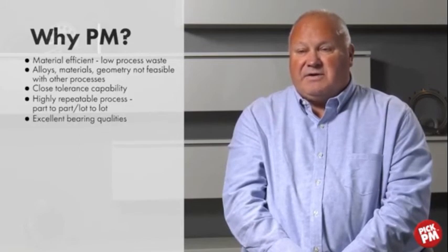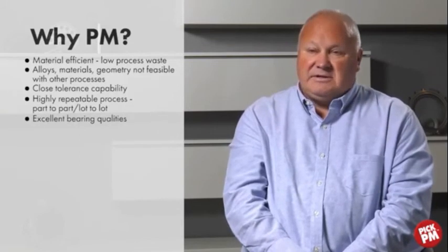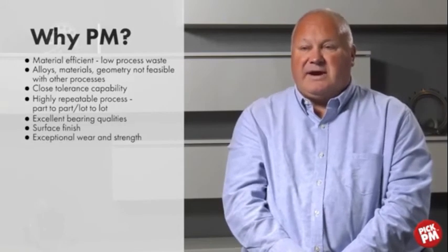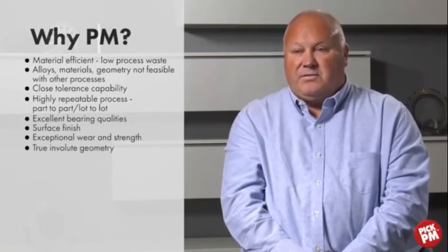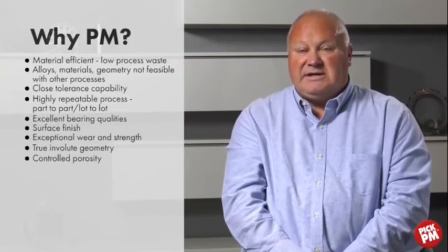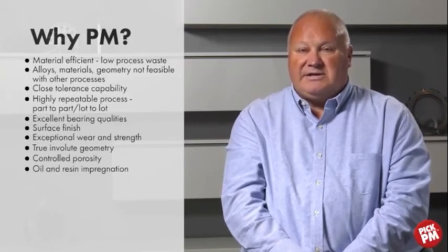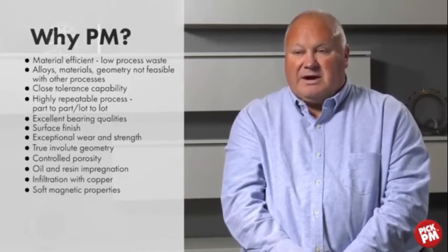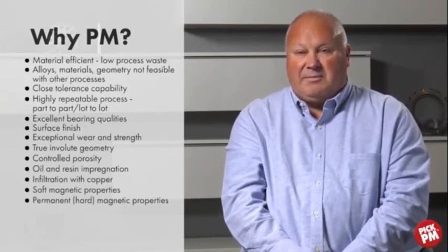Powder metallurgy provides excellent bearing qualities, very good surface finish, exceptional wear and strength, true involute forms on gears and splines, controlled porosity, oil and resin impregnation, infiltration with copper, soft magnetic properties, and hard magnetic properties.